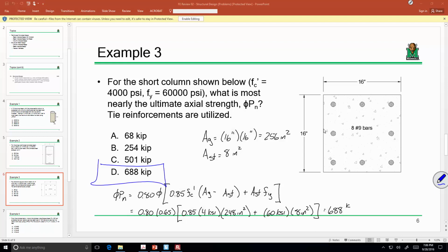If I only encase it about 1/8 of an inch in, I can yank it out. But if I encase it 12 feet into this massive concrete, I'm not ripping that thing out. There's a certain magic length where it doesn't matter if it's 10 feet in or 110 feet in, you're still going to fail the rebar before you fail the concrete. We call that the development length.